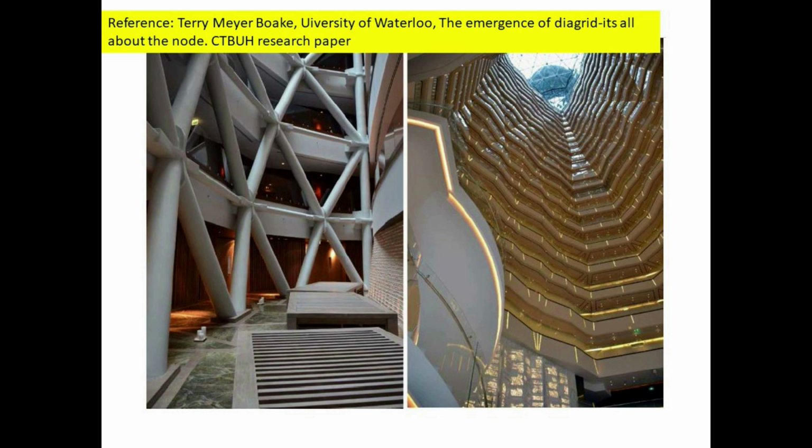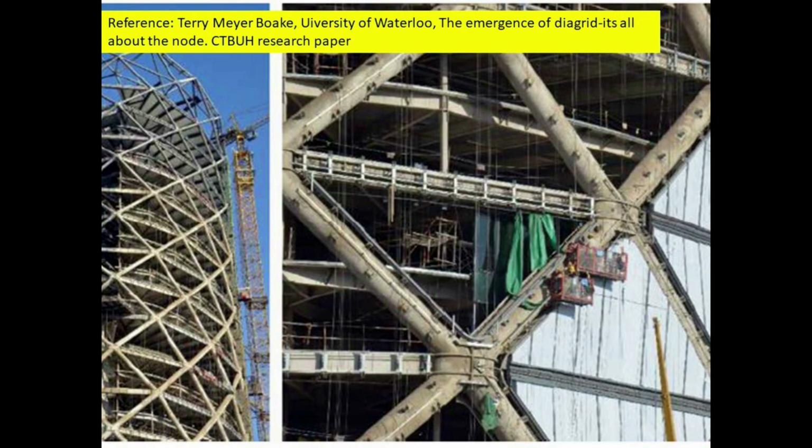Both towers use reinforced concrete cores to assist with stability due to eccentric loads, in the case of the 18 degrees lean of Capitol Gate. The extreme height in the case of Guangzhou IFC is also contending with seismic and wind loads. On the Poly International Plaza Tower, the choice of concrete-filled steel tubes and the resultant node design responded to the elliptical plan of the tower.